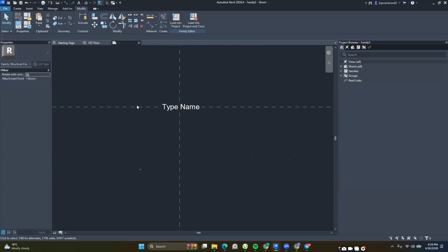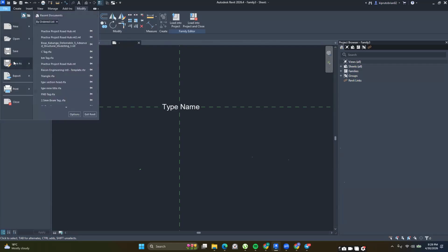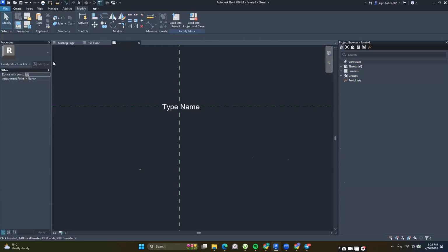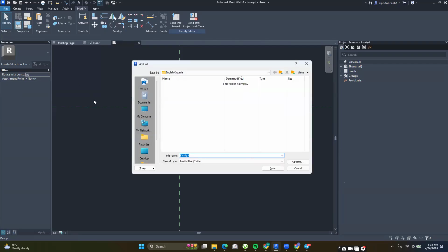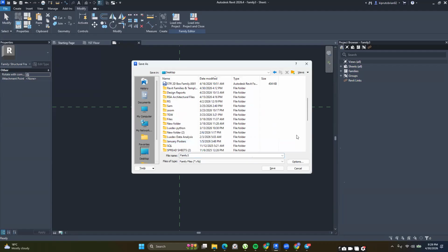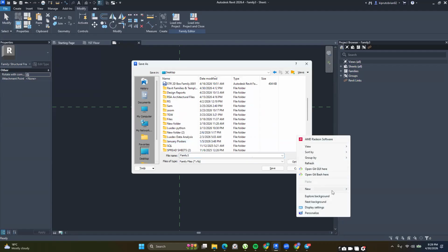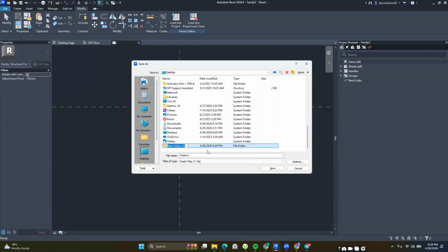Okay. I'm going to save it, and then you're going to play around with it. So I'm going to go to File, Save as a family. And then I'm going to save it in a folder. For now, let me make a new folder. Let me call it webinar families, just for the purposes of this training.